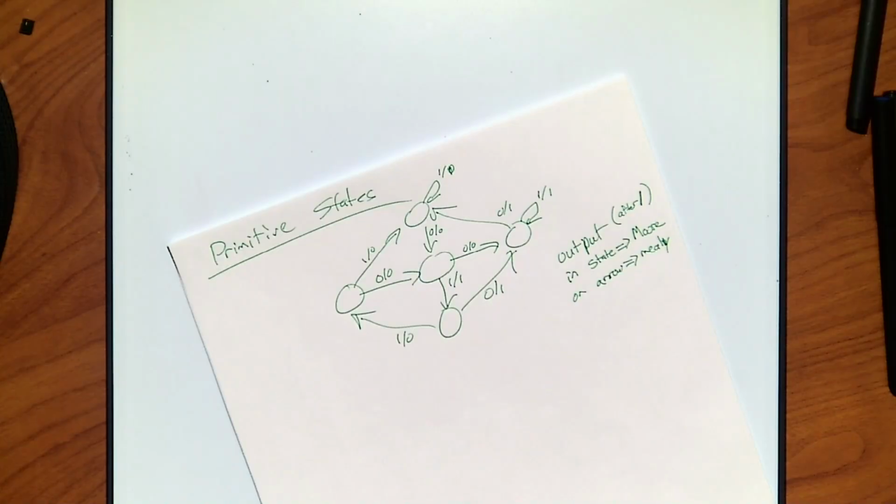Right? What if you already have a stable input? You know your inputs are good. You want that small thing because it's smaller and faster. So if I do my first layer as Moore's and everything after it is Mealy's, I'm probably good. So this is why I wanted to see the difference, because Moores make really good buffers coming in. Or if you ever need to resynchronize timing, Moores, very, very stable, right?